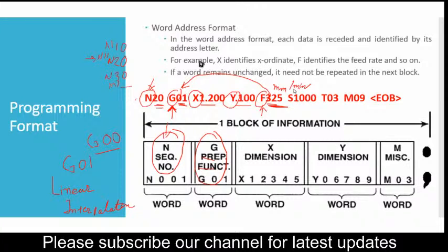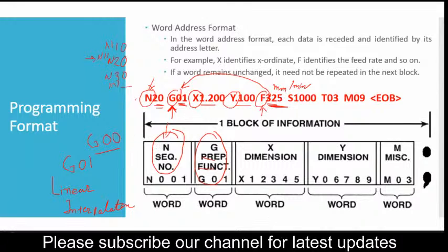So for the turning center DX150, that range is 24,000 mm per minute. If I write G00, then the coordinate will be reached at a particular location with a speed of 24,000 mm per minute. And if I have written G01, then it will reach at a speed of 325 mm per minute.